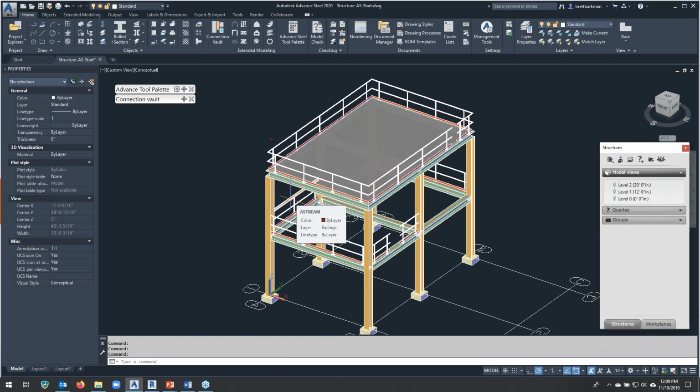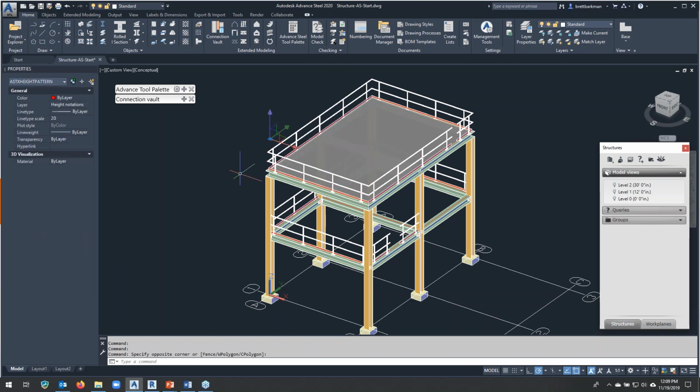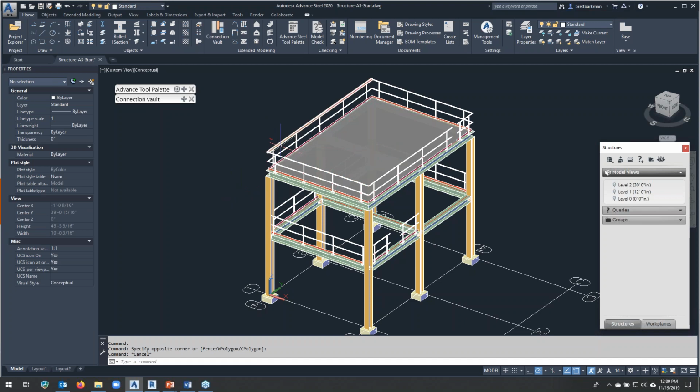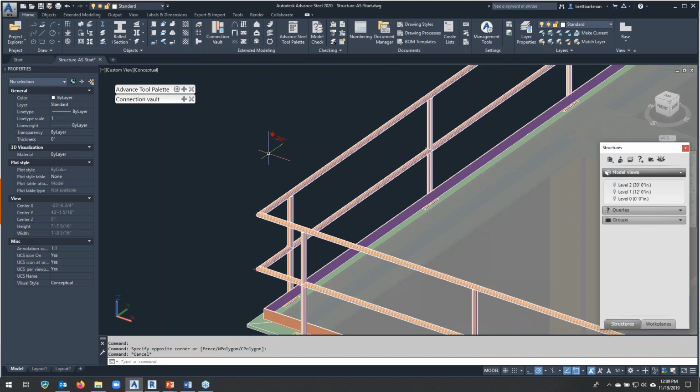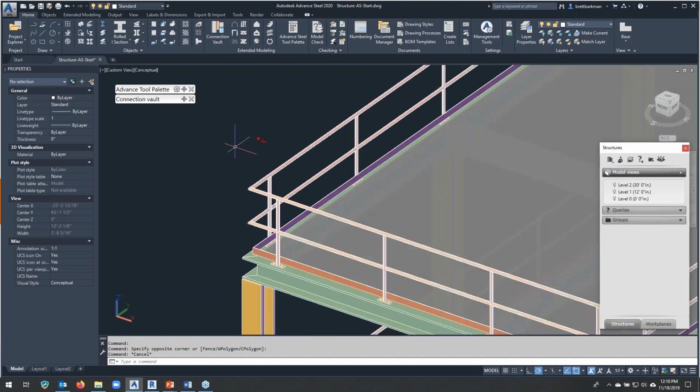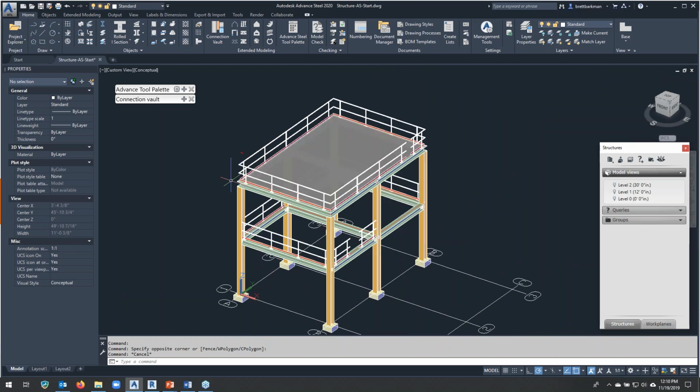Notice, though, that nothing really happens, but I do see that there is this one little red indicator that has appeared all of a sudden, and that happens to be the indicator for that level. Level 2 is now sitting at 30 feet, level 1 is at 12 feet, etc. But when I made that change, the only thing that moved was that indicator. So I raised the level, but none of the objects that are supposed to be on that level changed.